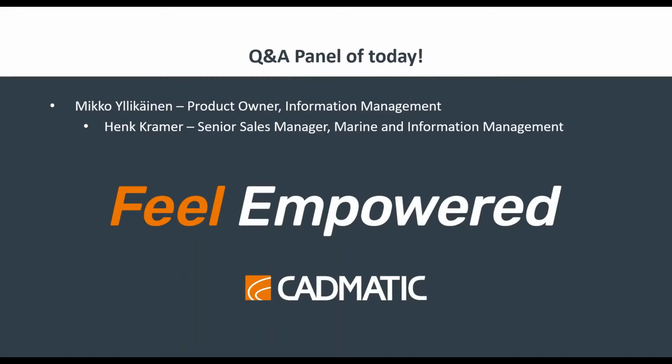Perfect. Then another question coming in from MS Holding. How are statuses you set in eShare relying on document revisions? Well, the document revisions, if you talk about the revision control, we only link to the latest revision. So when you publish a drawing to eShare, you can link to that document, and that is only the latest revision, because the model is also only the latest revision. The statuses you set in eShare, they're controlled in eShare, so they don't have anything to do with the document revisions. That is something which is completely controlled in eShare.